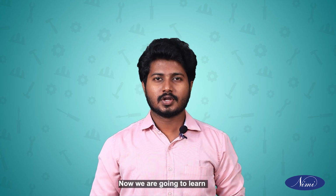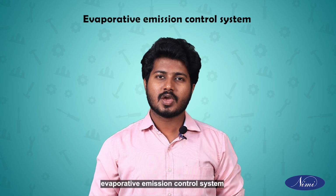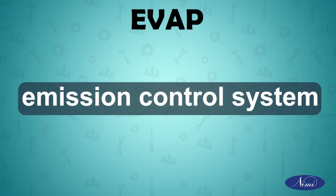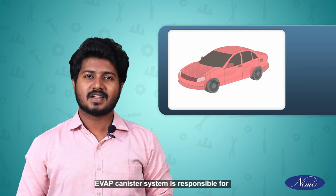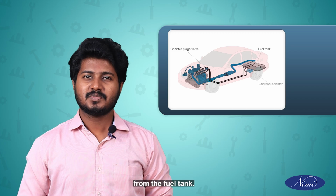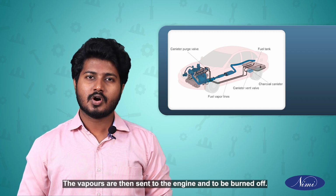Now we are going to learn one of the emission control system components called Evaporative Emission Control System. In short, it is called EVAP Emission Control System. EVAP Canister System is responsible for collecting and storing fuel vapors from the fuel tank. The vapors are then sent to the engine to be burned off.